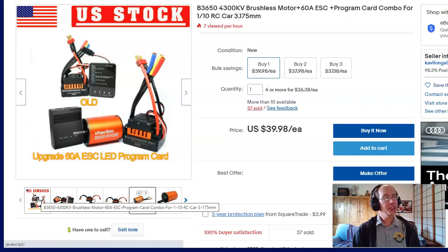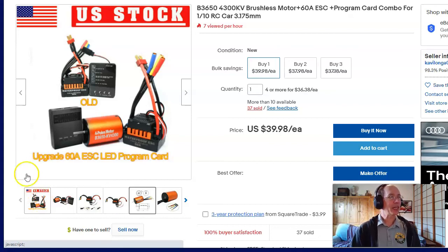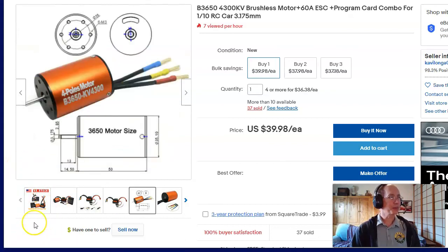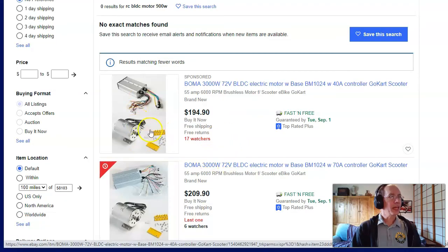And the question is, what do you do with it? That's the fun thing about being an engineer. I now have toys to play with. The challenge is, what do you do with it? And with the D2A converter, I can now output speeds anywhere between 0 volts and 5 volts, 0 to 4095. And with the driver, control a motor.